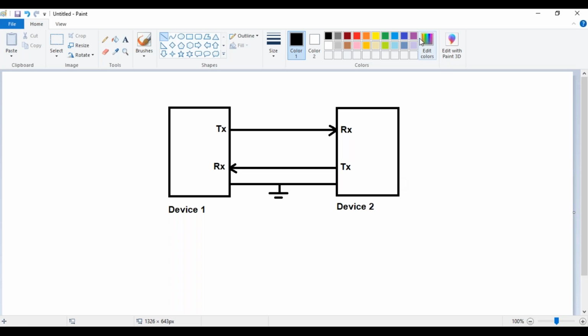So when you have two different boards, obviously UART is an example of an interboard communication protocol, where you are trying to establish the connection between chips of two different boards. So in that case, if you are not commonly connecting it to ground, there will be a connection being made between two, let's say, devices.